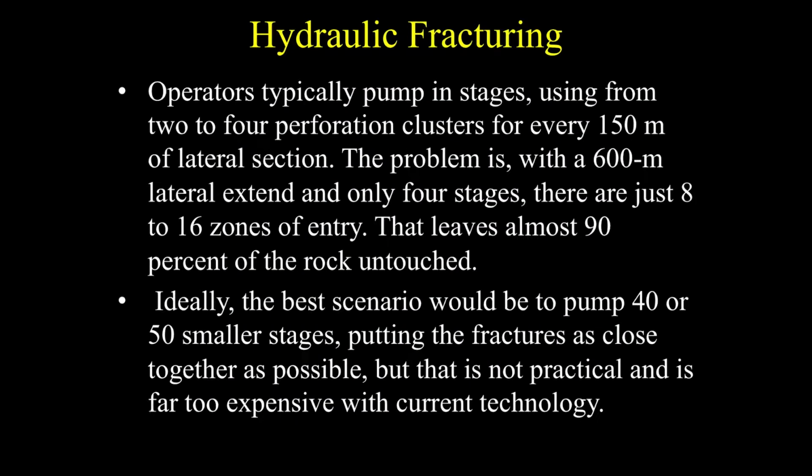Operators typically pump in stages, using from 2 to 4 perforation clusters for every 150 meters of lateral section. The problem is, with a 600-meter lateral extent and only 4 stages, there are just 8 to 16 zones of entry. That leaves almost 90% of the rock untouched. Ideally, the best scenario would be to pump 40 or 50 smaller stages, putting the fractures as close together as possible. But that is not practical and is far too expensive with current technology.